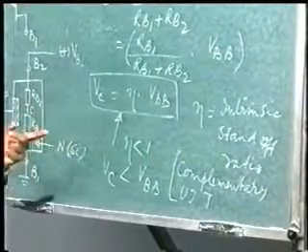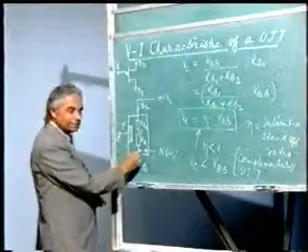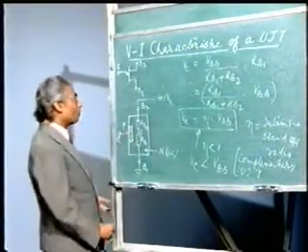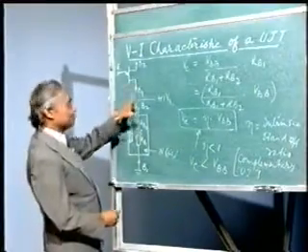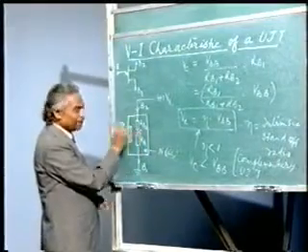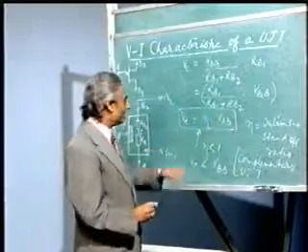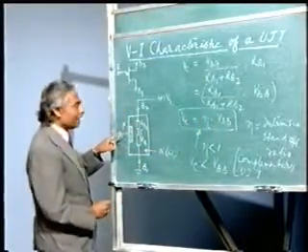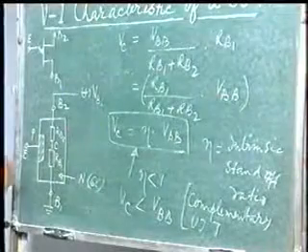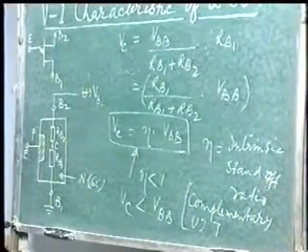So what is a complementary UJT? The complementary UJT is that device which will have P type of base and N type silicon diffused in it. Now what is happening when I am giving this supply? You see the potential Vc will be obtained here, and that will be given by this equation, and it will depend on VBB, it will also depend on spacing of the two, and it will also depend on the construction of the device. Now suppose I give a supply separately at this point emitter from external supply.